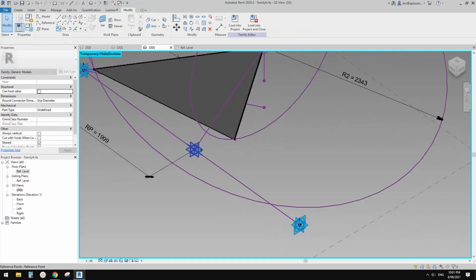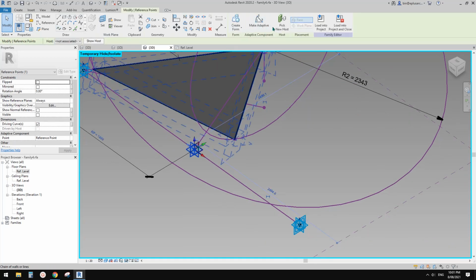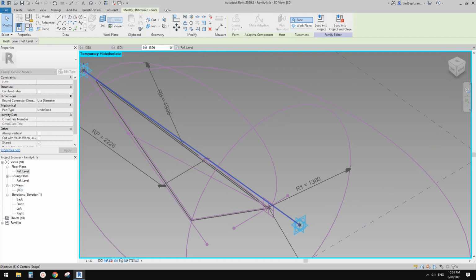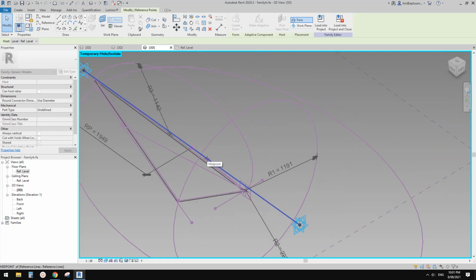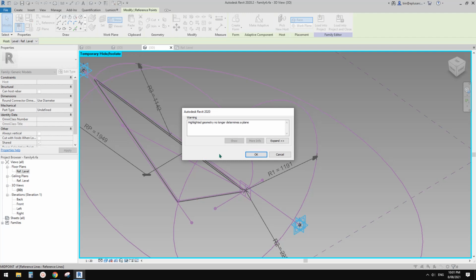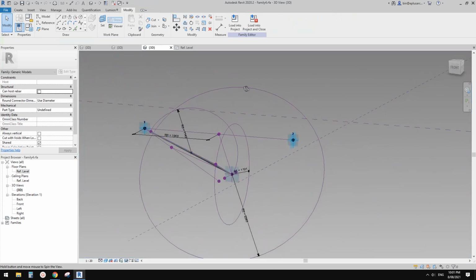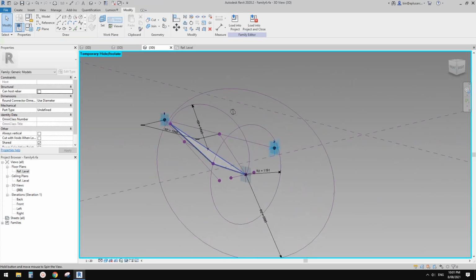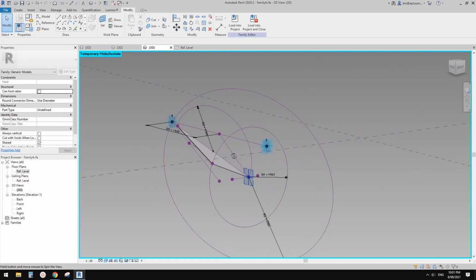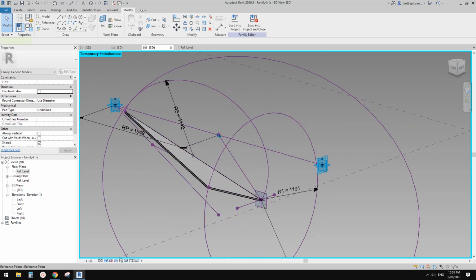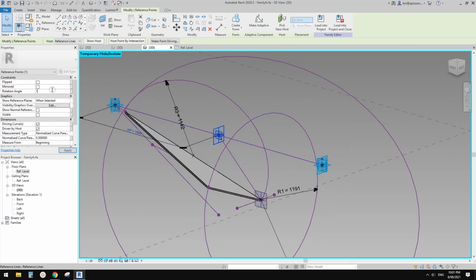And then we just need to select this point and pick new host, you can use SM. Okay, so SM will pick the midpoint. It looks like that should be fine. Just click OK. But looks like we need to rotate it somehow. So it looks like we need to rotate by, I'm not sure, let's try 180 degrees. Okay, so 180.